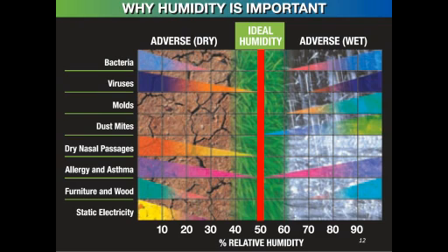Because for my window type, that kind of humidity level is too high for that low of an outside temperature. The outside temperature, as it falls, your inside glass temperature also falls. And your glass temperature can eventually get down to the dew point, and the glass will begin to sweat if your humidity levels are too high.